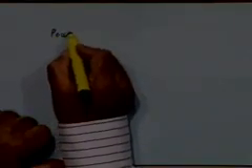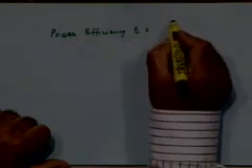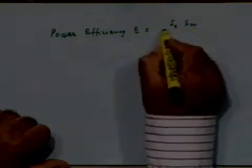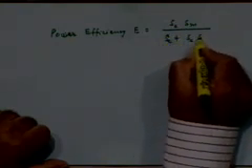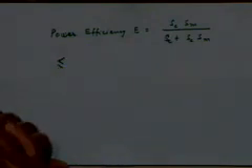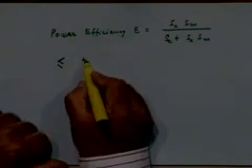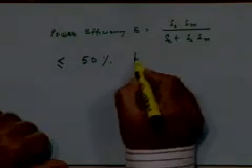What is the power efficiency there? So since the carrier conveys no useful information about the message, we can define this factor power efficiency, call it eta or whatever notation you like to use, which is this product divided by S sub C plus S sub C into S sub M. Typically, this value will be less than 50% for any message signal.